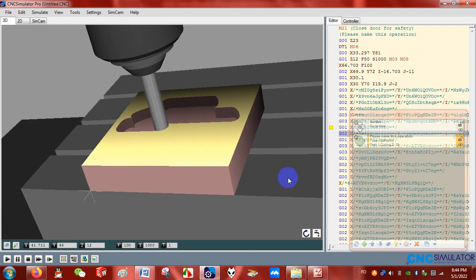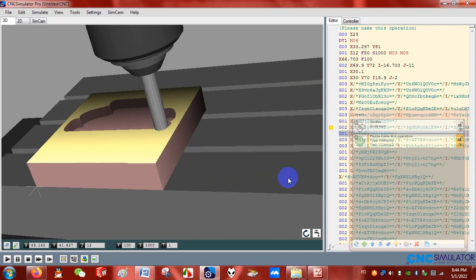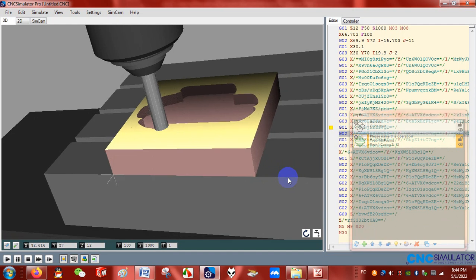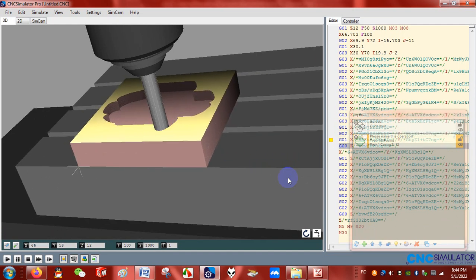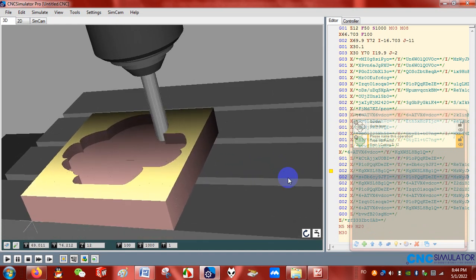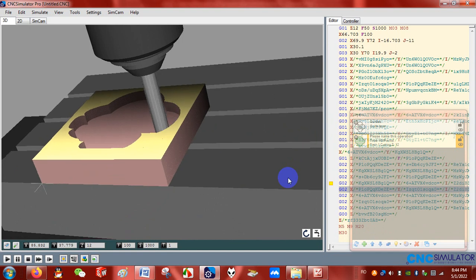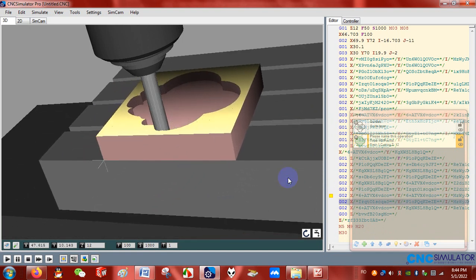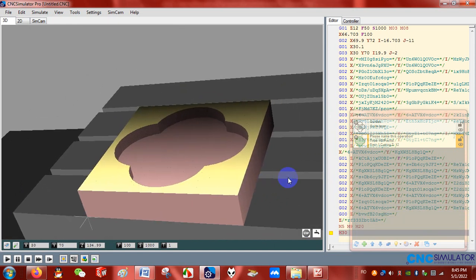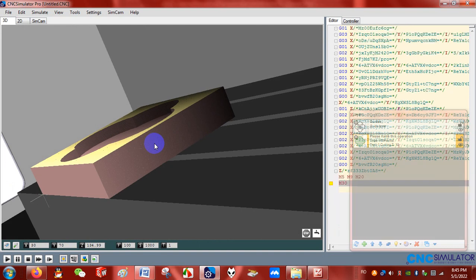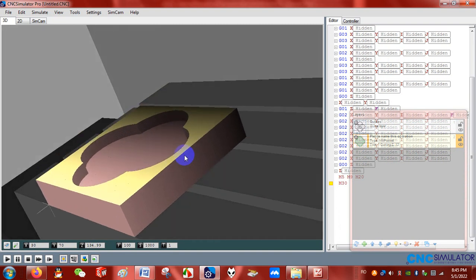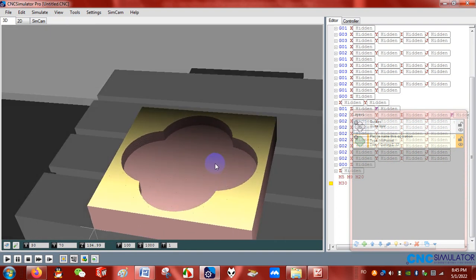So how can we say how much bigger it is? It's 20 minus 12, and it's 8 millimeters deep. 8 millimeters deep. So we can change these parameters of machining by changing the layer parameters when we select the cutting tool machining parameters. Here we go. So as one can observe now, the cutting depth here is bigger, from 4 millimeters before to 8 millimeters now.